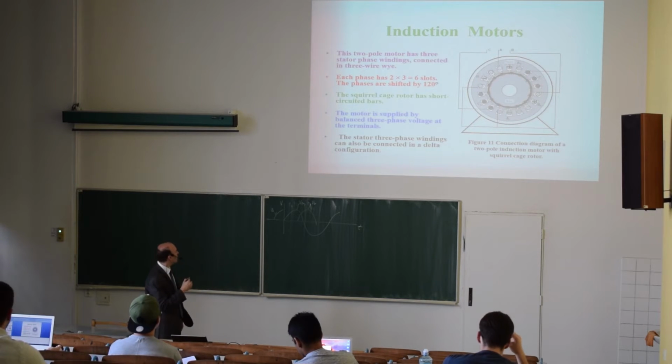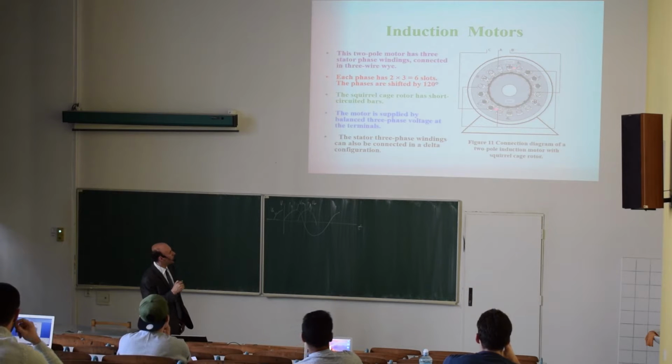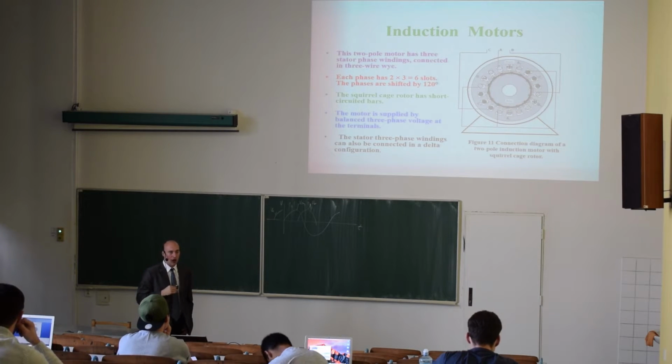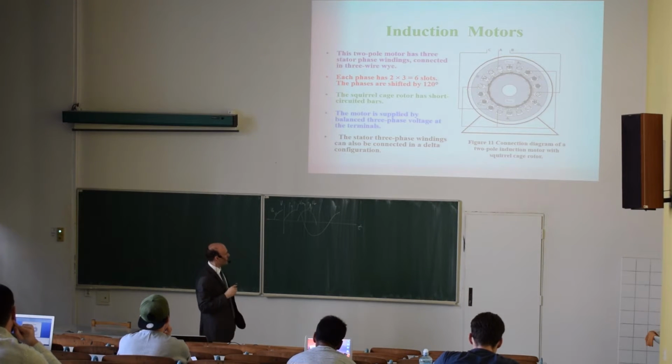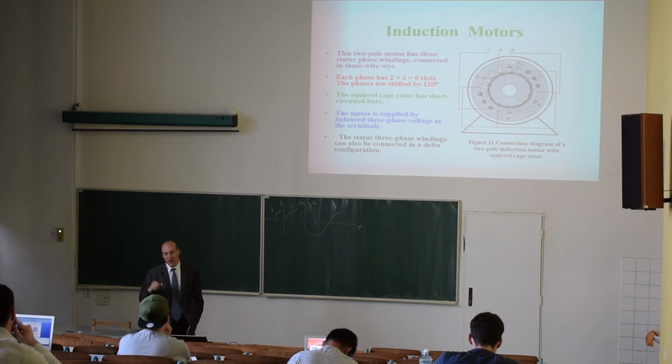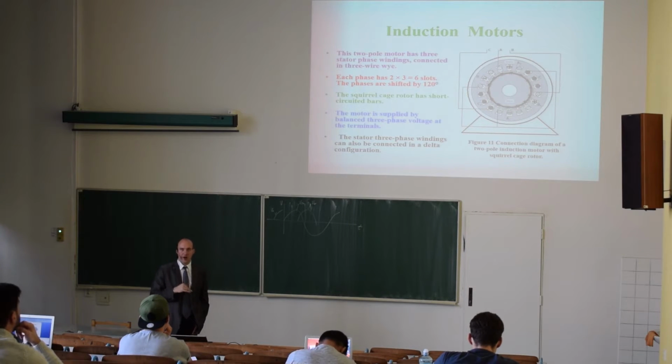Okay, so here we see that the torque of the induction motor will depend on the difference between the speed of the rotor and of the stator magnetic fields. So the torque speed characteristic of an induction motor will have a specific shape, and the torque will be a function of speed.